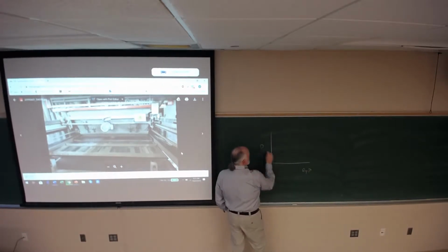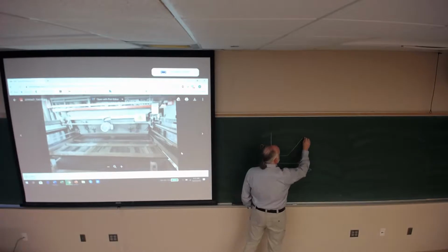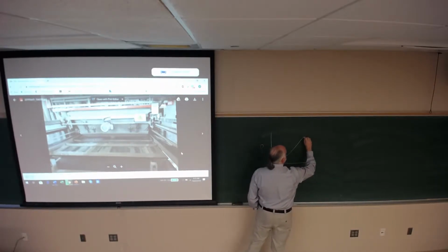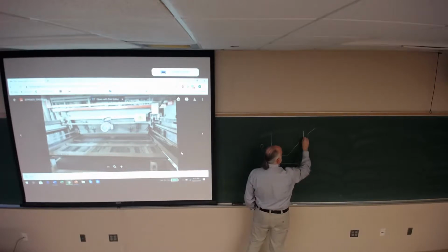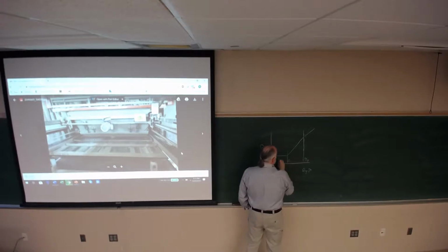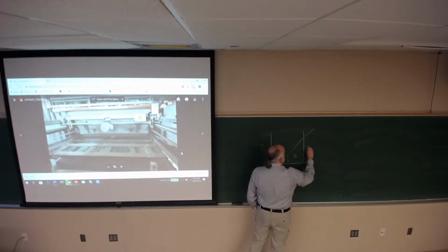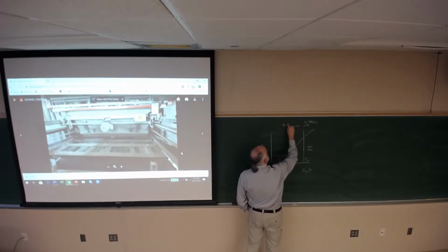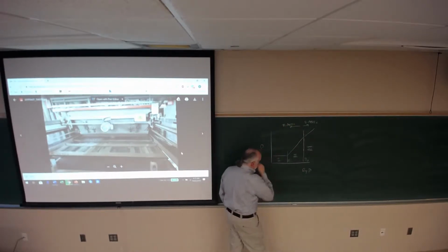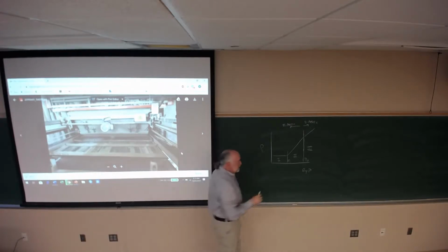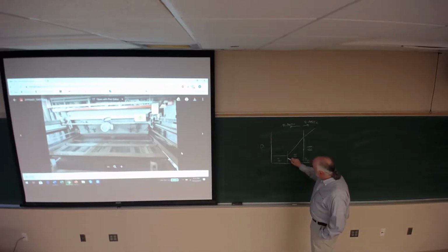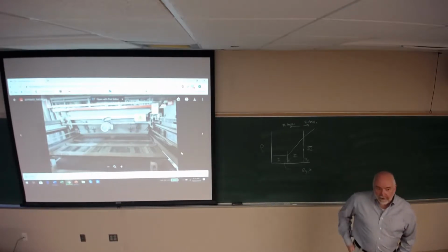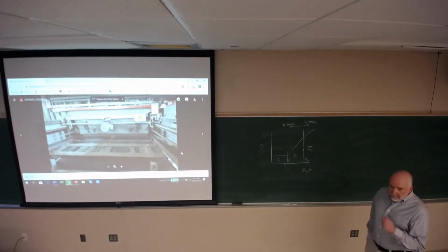Log pressure versus density. The curve looks like this, and actually this difference here is very shallow. P1, P2. This is elastic, and this is plastic deformation, which we talked about in class last week, or yesterday, whatever it was. This transition, P1, is called the onset of granular deformation. So it's where the granules start to break down.